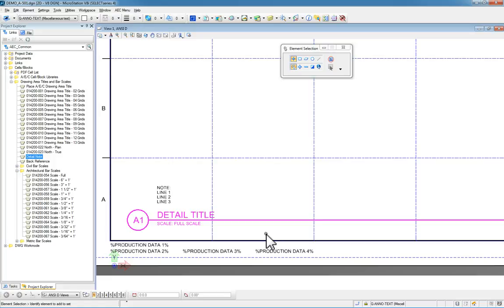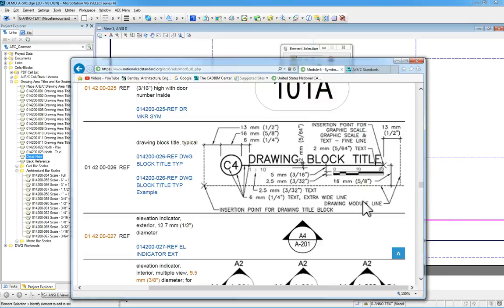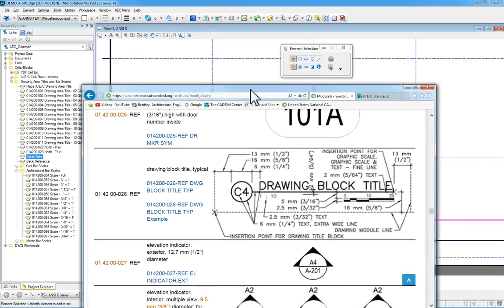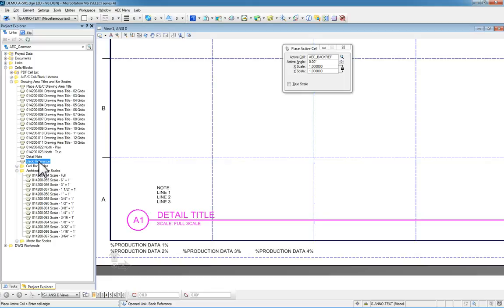There are some places that use back referencing. Since there is nothing in the National CAD Standards to describe how a back reference would happen, and to maintain the structure that the National CAD Standards calls for, we added another cell that if you choose to use, there's nothing requiring it, but there is a back reference cell, and that one again snaps to the intersection of the grid.